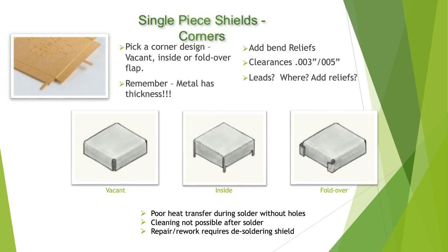If you think about it, basically assembly, heat transfer, and cleaning, they all lend themselves to single-piece shields. Just make sure you've got those bases covered and you can put the shield on after the board's been soldered, if that's an option. Then cleaning and heat transfer are not an issue for you.